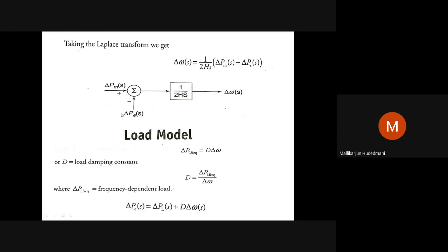In that regard, the electrical load, whatever we present to a generating area, delta P or P, needs to be modeled suitably depending upon the sensitivity of that load to the frequency and insensitivity of that load to frequency. That is put as delta P, maybe an infinitesimally small change in electrical demand, given as small change in electrical load which is insensitive to the frequency and sensitive to the frequency by having D of that area mentioned.